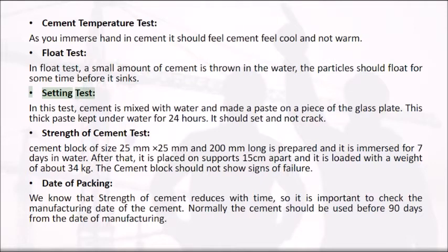Setting test. In this test, cement is mixed with water and made into a paste on a piece of glass plate. This thick paste is kept under water for 24 hours. It should set and not crack.